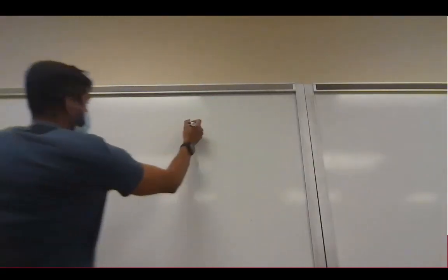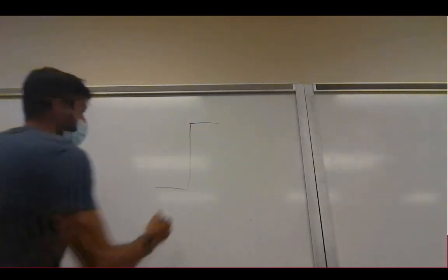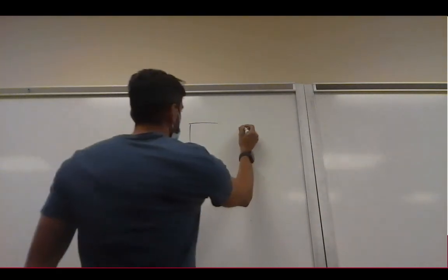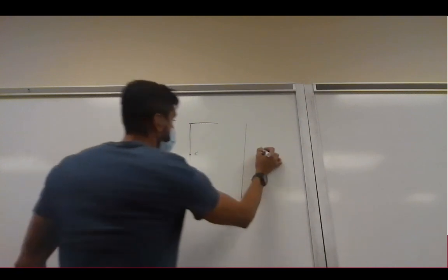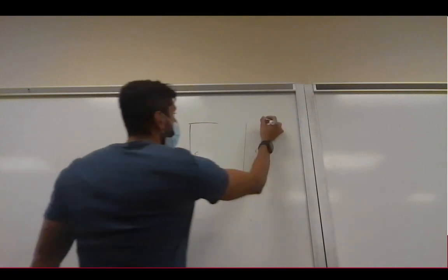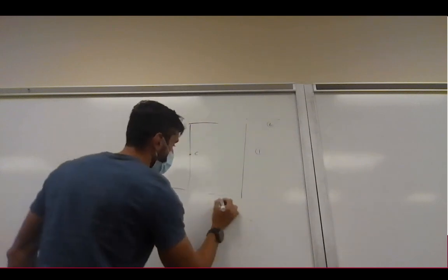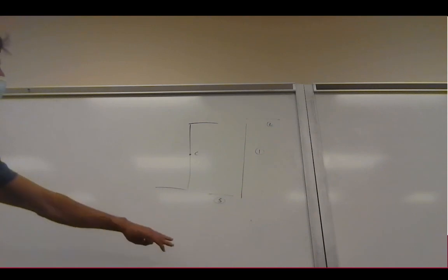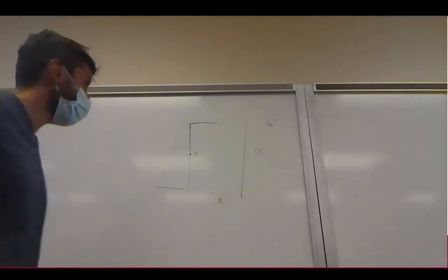So again, say for example, these are our coordinates. This is our cross section. We have our centroidal axis here. What we do is say this cross section is 3 segments: our first segment, our second segment, and our third segment. Because the moment of inertia can be viewed as a summation of the individual parts, we can do this.